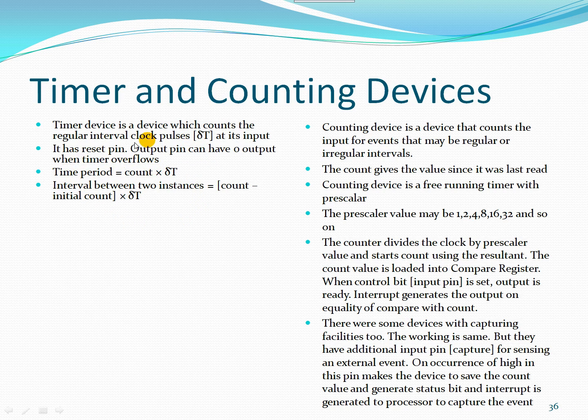This is going to be a common thing, that is, the output pin will be having the output as 0. Whenever it is given 1, the timer will be restarted, and the reset pin will also be given 1. By that time the timer will be restarted and it will run up to the maximum count which is set on that particular timer.